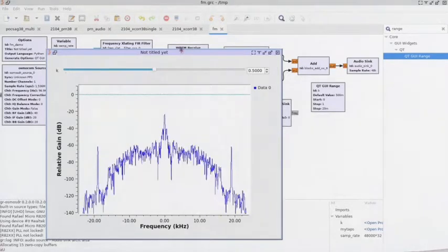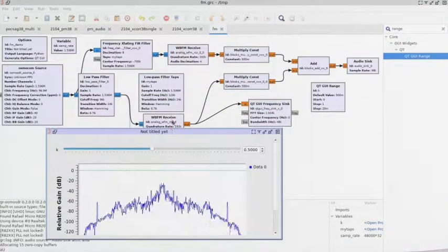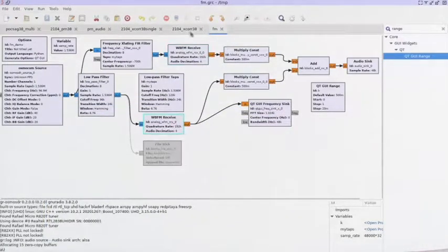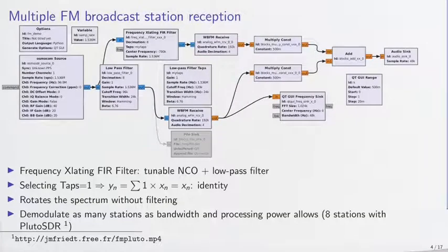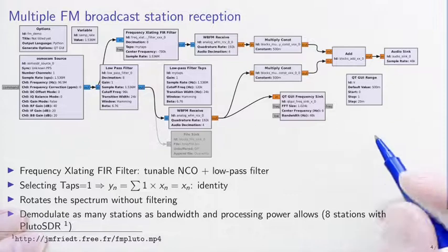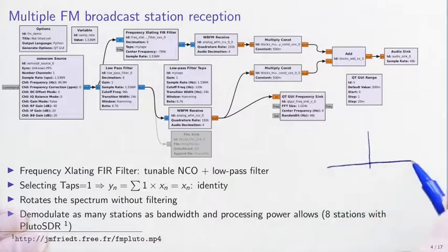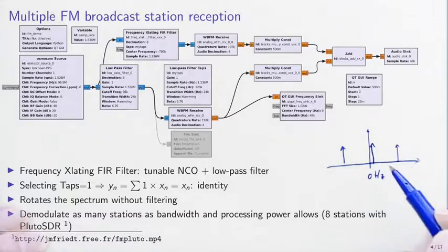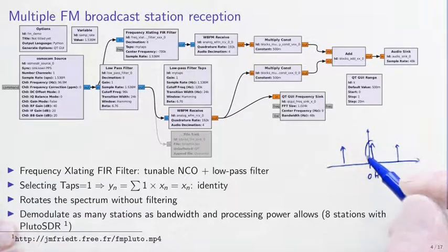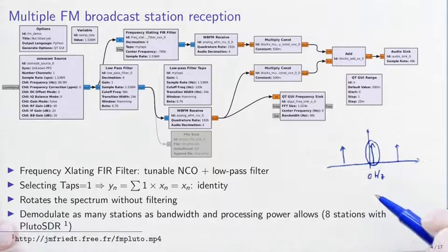Both stations. So with this, we demonstrate how we can receive two stations simultaneously and analyze multiple data streams available within the sampling frequency. So again, remember, the most important aspect is that whatever signal can be found within baseband, so after bringing the radio frequency signal to the area centered on 0 Hz, all these signals that we saw earlier, so we had 3 FM stations, and in this example we were recording the center frequency channel.